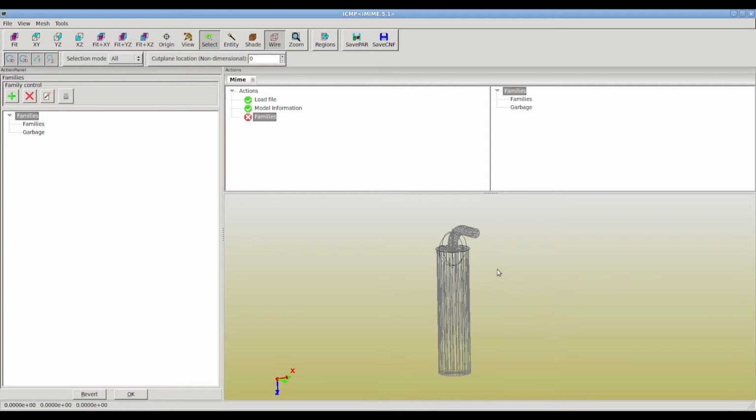In order to pick items on the screen, there are different modes. Actually, there's three different modes. You can click on an item, unclick using the right mouse button, or you can draw a box on the screen. If you start from the left side and drag the box, every item that is completely enclosed in this box will only get picked, like so. You can see that this long wall surface or cylinder surface did not get picked because it was only partially inside the box.